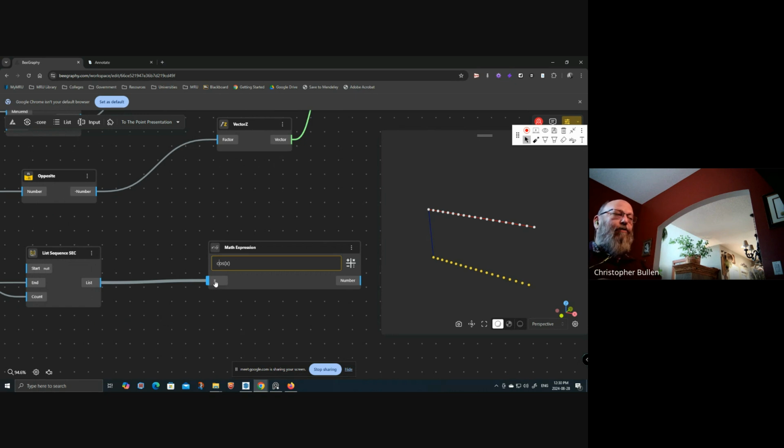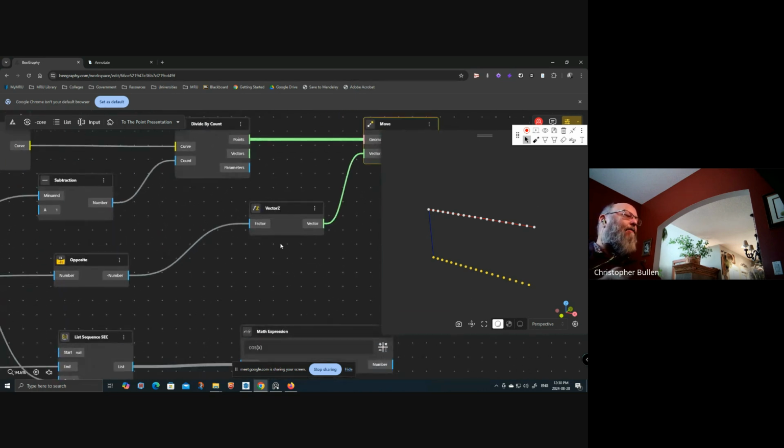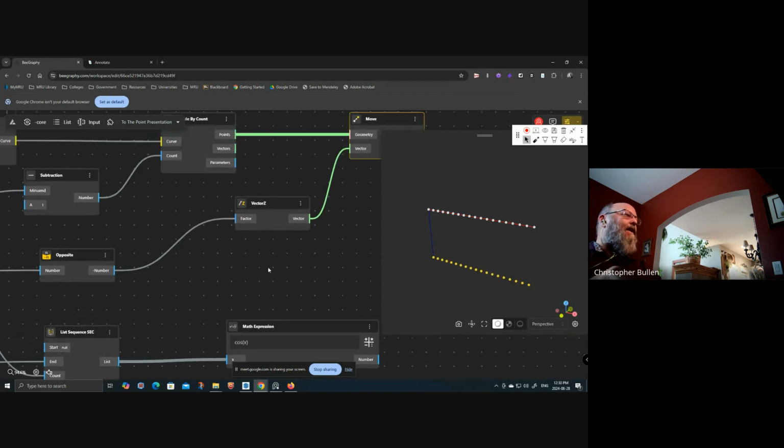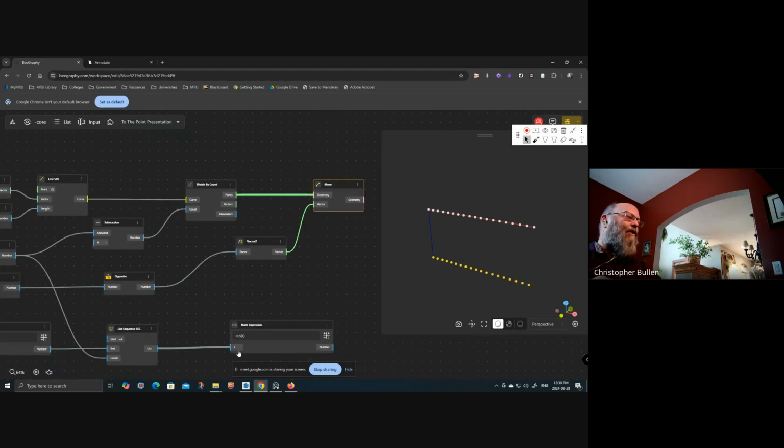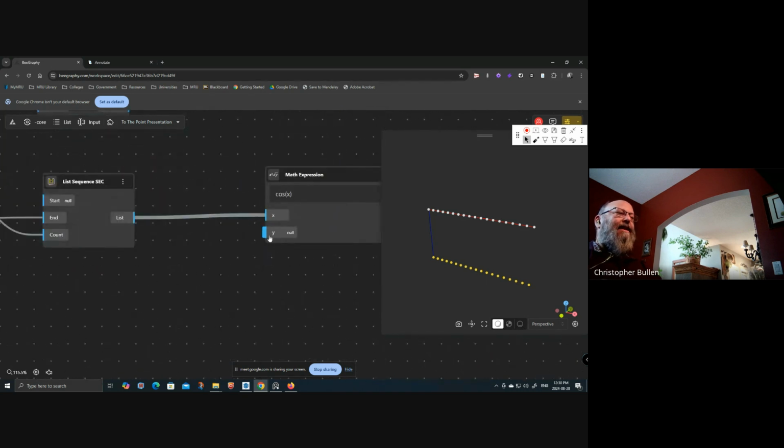So I'm going to add another port here, which is going to be Y. If you come down here on X, we click on this. And if I pan up here so I can see this, let's zoom out. It's way up there. We want to add a port. So I just clicked on that, and I'm going to say add a port. This is going to be our amplitude, and I said it's going to be 1 meter.